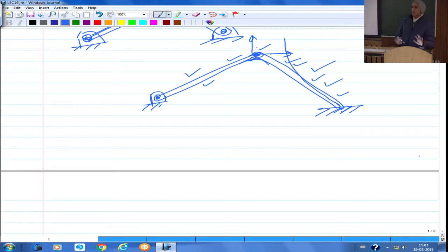So essentially, if there is a bending resistance, so there is a bending moment coming onto the structure in addition to axial force, then you need to model using frame element, otherwise you can use truss. Yeah. So suppose the first problem we model with the beam element, frame element, then what will be the effect on the result?